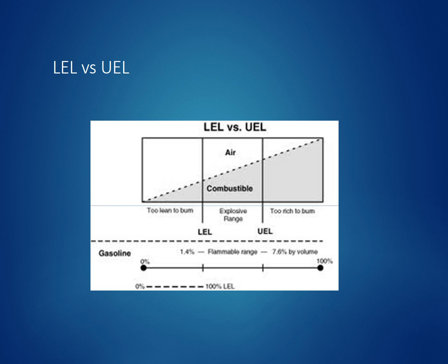Now, as industrial hygienists or occupational health professionals, we usually deal with things like benzene at 1 part per million or formaldehyde at 0.75, or maybe xylene and toluene at 100 parts per million. However, when we're talking about flammable ranges, we're talking in the tens of thousands of parts per million.